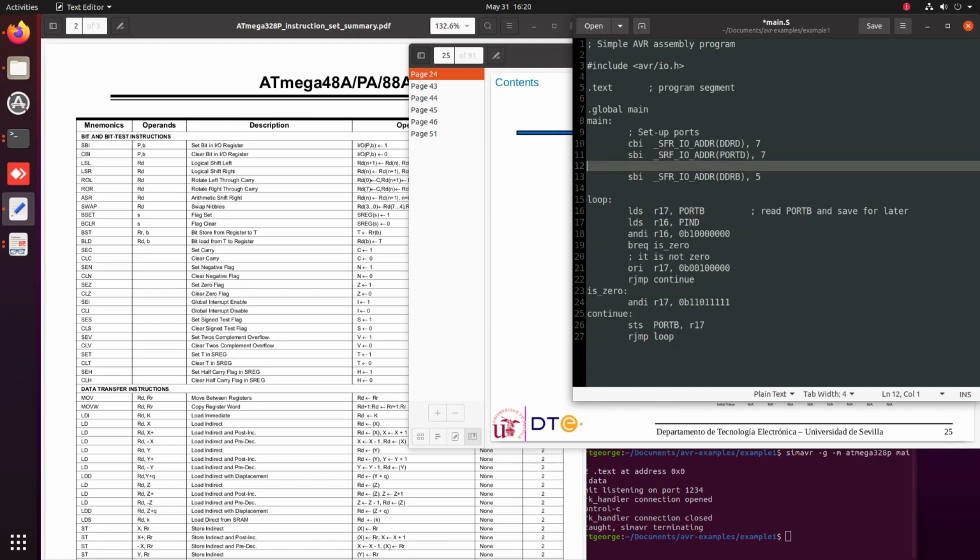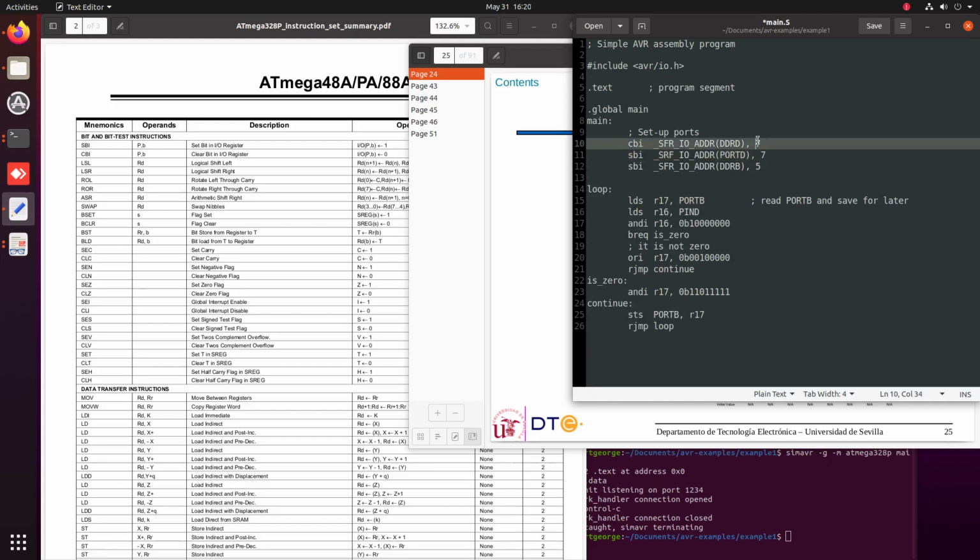Okay, so now actually using these numbers here is not a good style of coding. You know, never use constants directly, because in the future those constants may have to be redefined somehow. So the standard definitions already have defined names for the pins in the ports. So we may use PD7 here and PD7 here. This is actually the same because PD7 is equal to 7, PB5 from port B is equal to 5, but supposedly it makes the code more clear, using these things here, okay?